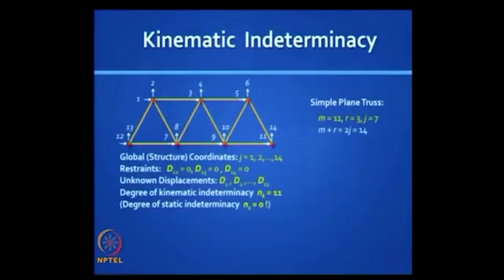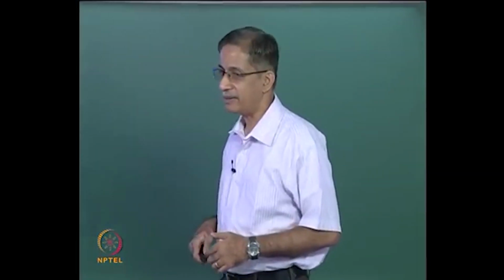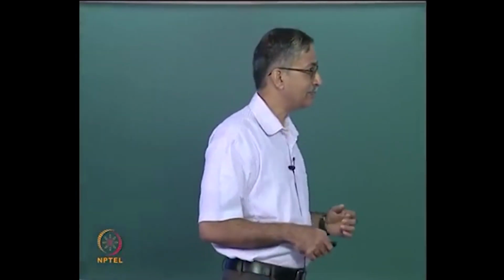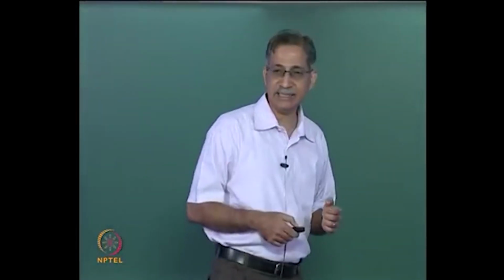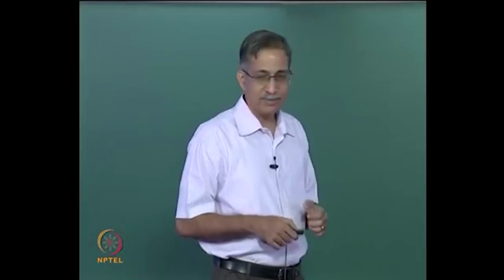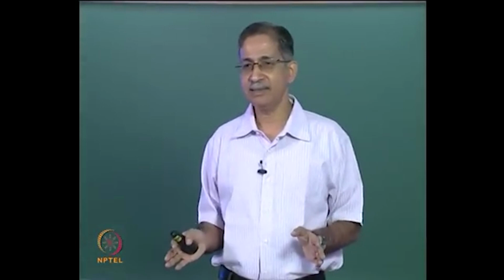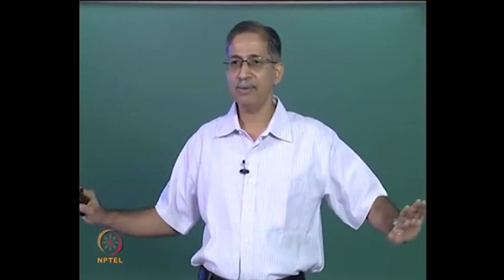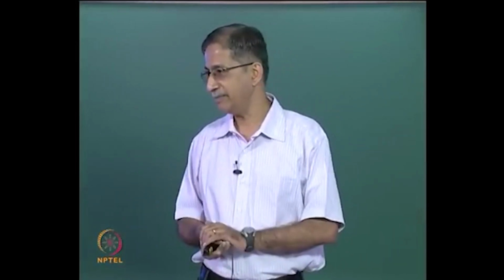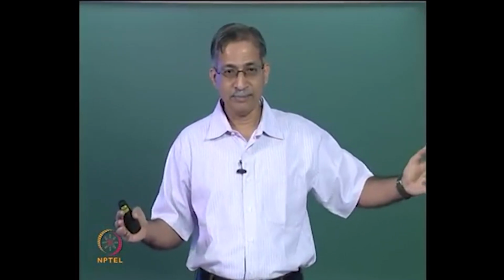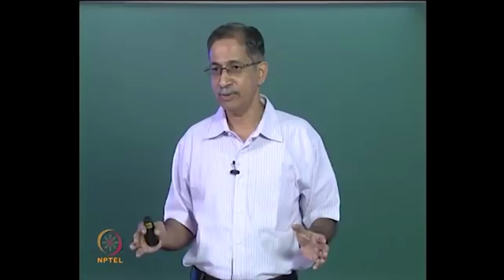Now you are familiar with static indeterminacy. It is important to know this new term called kinematic indeterminacy. It is very simple. Our real task in structural analysis is to know everything about the force field and the displacement field, right. In the force field, you saw earlier there were some knowns and some unknowns.